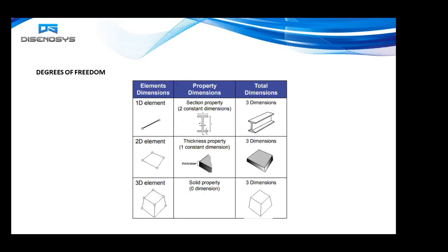And if you take a beam element, you will have ux, uy, and rotation about the z axis. The rotation about z enables your bending and shearing properties. That's why for a truss problem, for any bridges, steel bridges or anything, it will have only the axial displacement. It will not have any bending. So for that kind of problem, we use a truss element. And if you want to know about the bending property of your structure, you have to go for the beam element. Beam element will have 3 degrees of freedom.